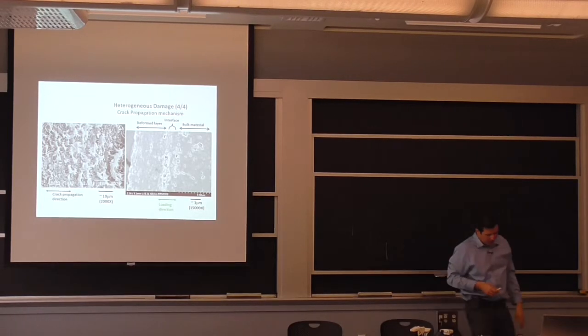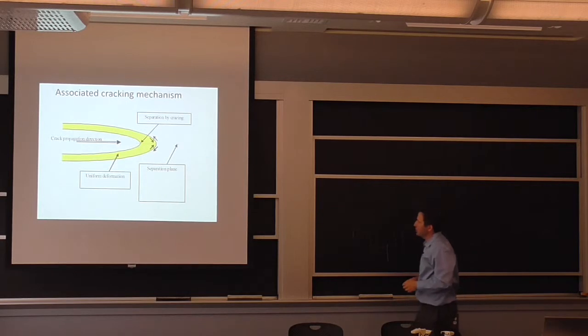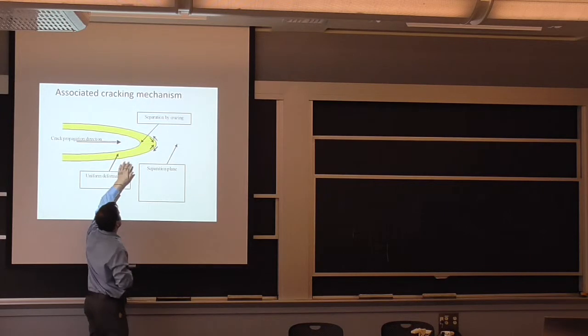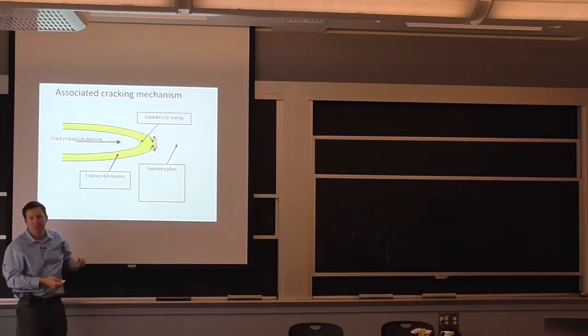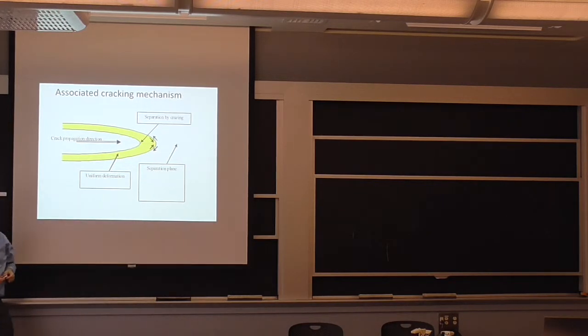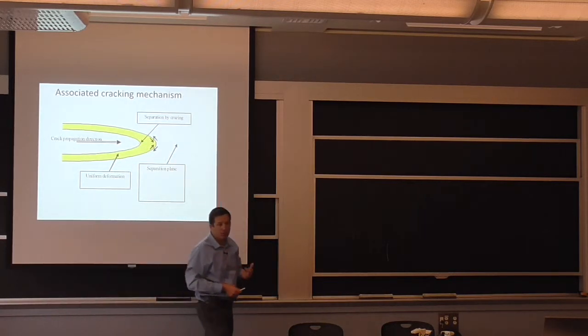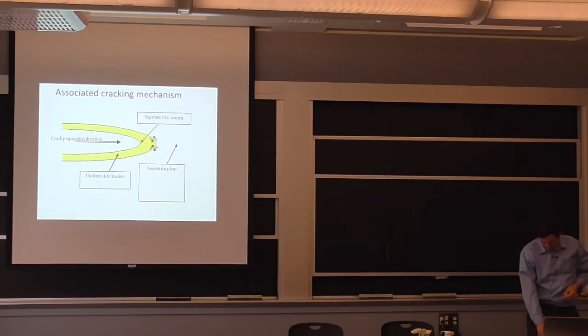So essentially it points to the first process taking place at the tip of the crack being plastic deformation, uniform deformation in the bulk that allows the large molecules to go one way or the other, but again, they very rarely break. So they get sheared and moved from one side to the other, and you have the blunting of the crack. And somewhere in there, of course, you start forming voids, but it's not the only thing that's taking place. There's just a lot of deformation.